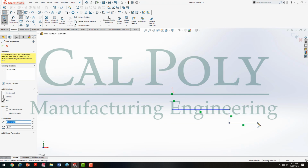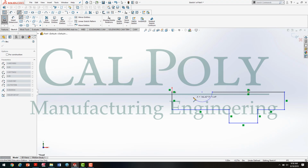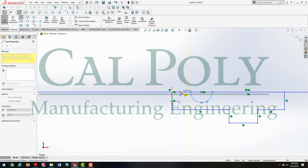Draw another horizontal line, a vertical line, a horizontal line, and a vertical line. Then I'm going to come to right around here, click my left mouse button, then if I flick my wrist in an arc direction, it creates an arc. I click my mouse button, and I'm back to my line tool.